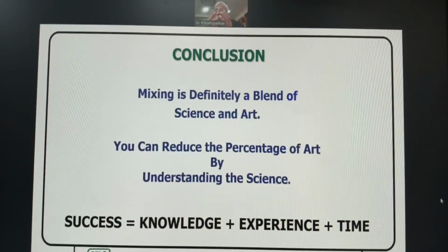And with magnification, you can see whether the surface is dull, whether the surface is shiny, or whether something is melted within the surrounding material, an undispersed material. You can say whether it is undispersed material, an air entrapment, a moisture entrapment, or solvent. So these are simple techniques to find out the root cause of the day-to-day process problem. Always we try to jump to the compounding, and that is not always true.